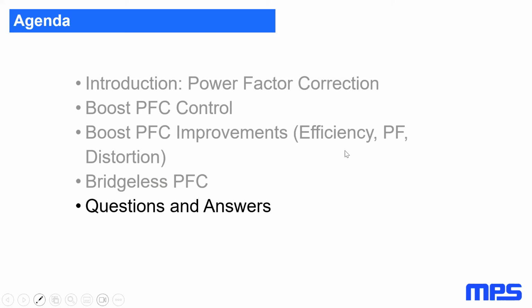So in reality, for a given point of operation, it's most likely that the input filter will be bigger on the totem pole PFC than on boost PFC, although there are some enhancement techniques that can be used to minimize that. But the quick answer is yes, there tends to be higher EMI content due to common mode in the totem pole PFC.